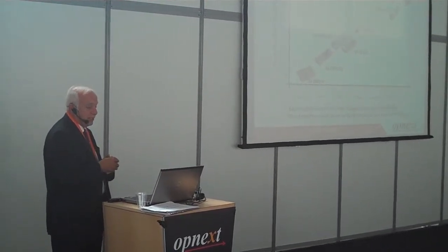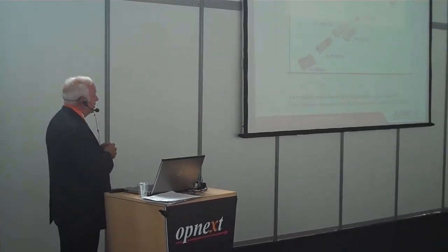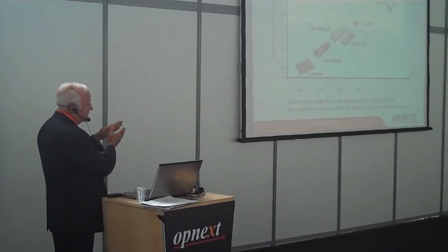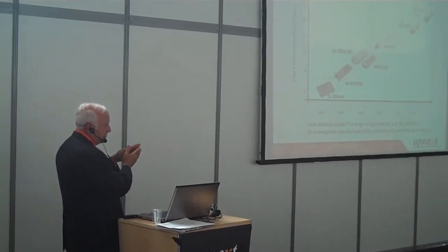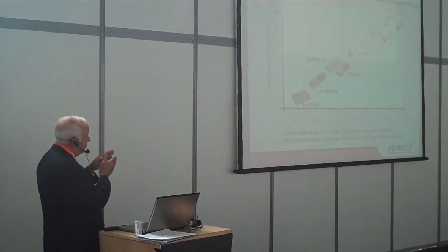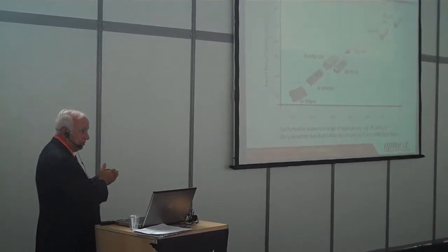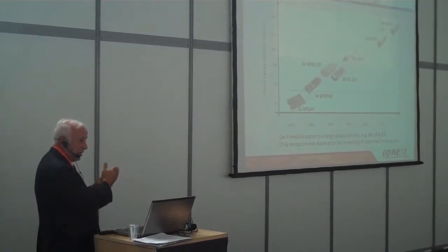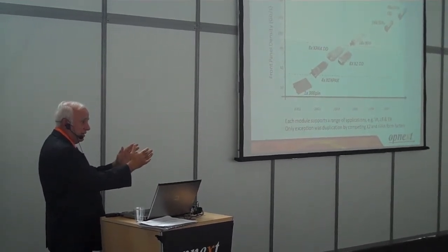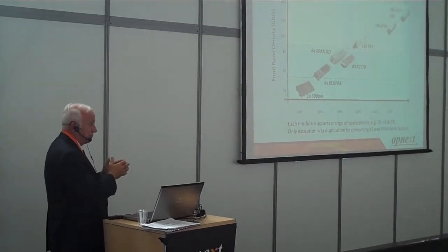And then density coming in, SFP+ is the next one coming in, and then there's another one, SFP+ double density. So you can see what's happening is they're getting smaller, less power, and cheaper. But there's another key factor that we can't forget: during this evolution, there were designs being done on the system side of the house to take certain functionality out of those modules. So a trade-off back and forth, how much functionality you leave in the module versus the system design. And again, it was a cooperative effort to really get the lowest cost solution.